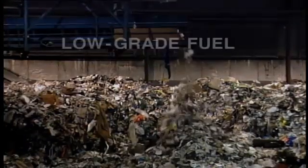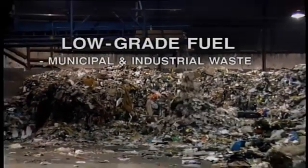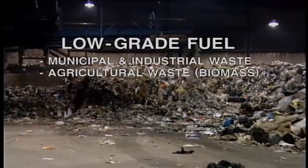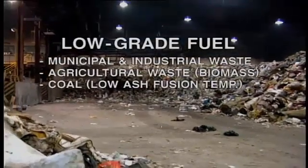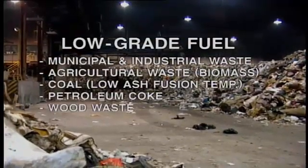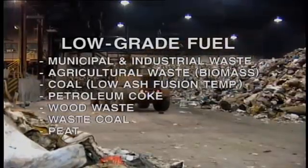It results in heavy slag formation on boiler tubes, superheaters, and other areas. This often leads to blockage of gas flow through certain sections of the boiler, as well as loss of heat transfer and consequent reduction in boiler output. The term low-grade fuel is used to describe such items as municipal and industrial waste, agricultural waste known as biomass, coal with low ash fusion temperature, petroleum coke, wood waste, waste from coal treatment facilities, peat.